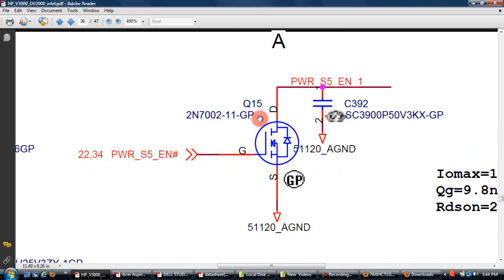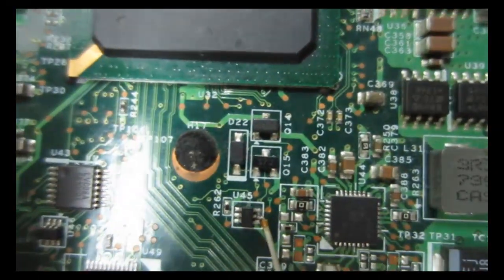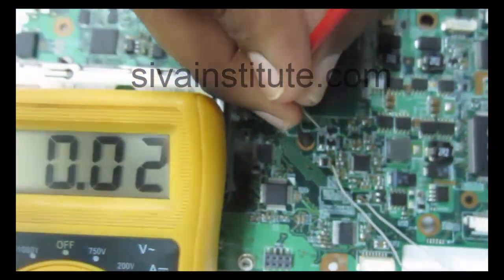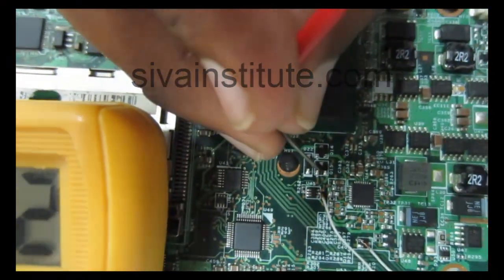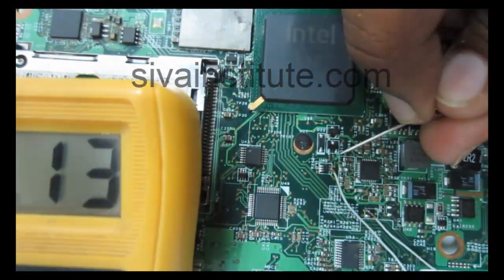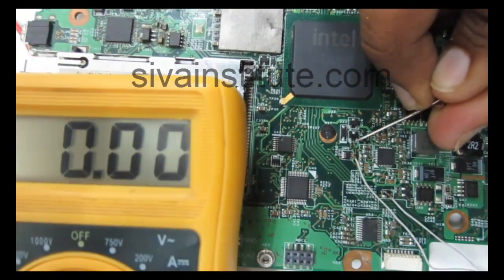See here, this is Q15. Without the SPI command, gate voltage is 5 volts, drain voltage 0. With the command, this voltage goes to 0, and this voltage comes out from this drain. This is the Q15 transistor. We will see voltage without the SPI command. First gate voltage 4.9 volts, drain voltage 0. Source voltage 0. Source is already grounded.